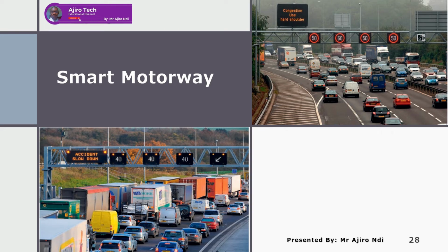If the road becomes very busy, the system can automatically lower the speed limit or open the hard shoulder to traffic. Okay. Now, the computer can reduce the speed limit from 70 miles per hour to, for example, 50 miles per hour, okay, which slows traffic down and reduces the chance of traffic congestion. The decision made by the computer will often remain free of human intervention unless the decision appears to be unusual. However, computers are not programmed to react to a crash or allowed to close lanes. Okay, so this is another disadvantage.